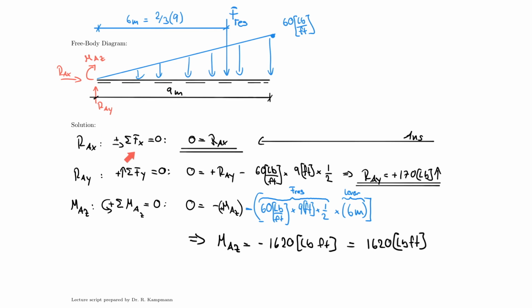Don't fall into the trap to think negative means always clockwise. In fact, you see here, this is actually clockwise, right? I assumed it clockwise, which usually would be negative as indicated here, because counterclockwise is positive defined here. But I just found that this here came out to be negative. That means I assumed incorrectly here, and therefore it turns the other way around.